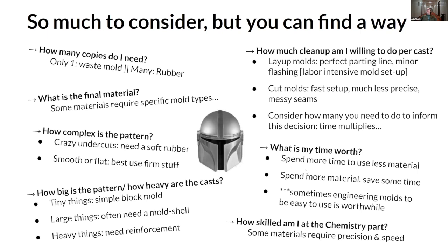You spend more time to use less material and more material to save time. And taking the time to engineer can really pay dividends in the end. I can't reiterate enough, start out simple. If you're using something that requires some sort of weird mix ratio and you don't have enough time, like it gives you 2 minutes to work, that is not a beginner material. You want a lot of working time and an easy mix.